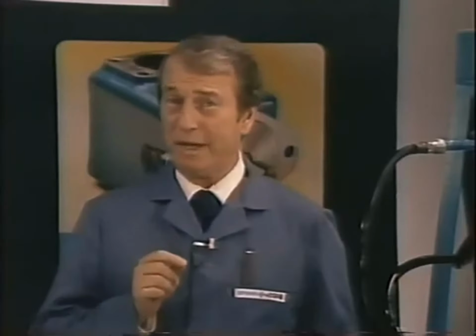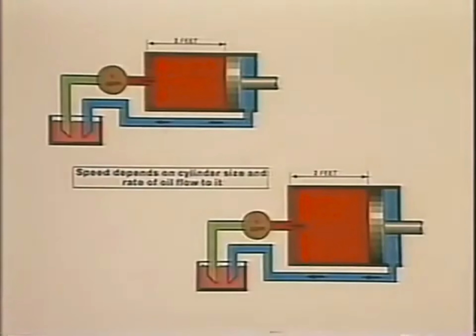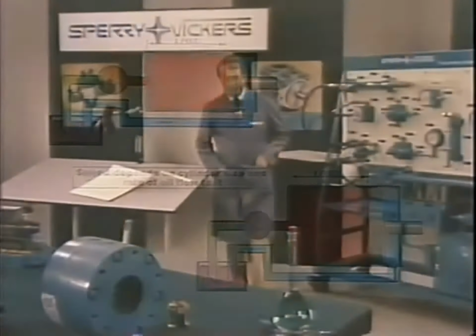I suppose you already know that increasing the relief valve setting doesn't increase the speed of a cylinder or motor. It's the amount of oil available and the size of the actuator that determines speed. That's why little cylinders move faster than big ones in the same system. Increasing the pressure will let you clamp tighter or move a heavier load, but be sure you don't try to exceed what the system is designed to do.